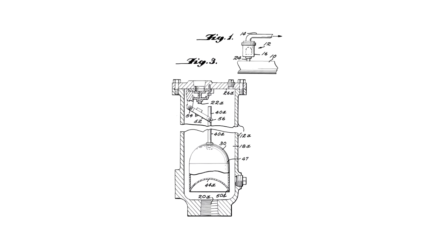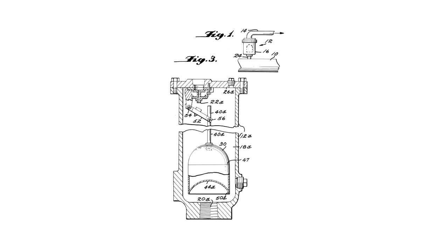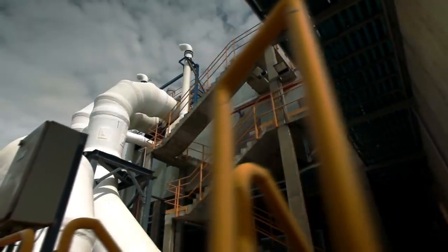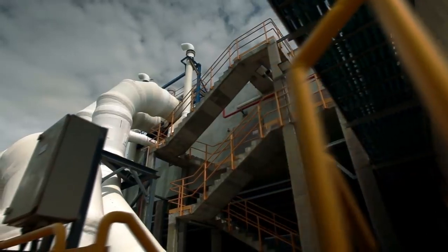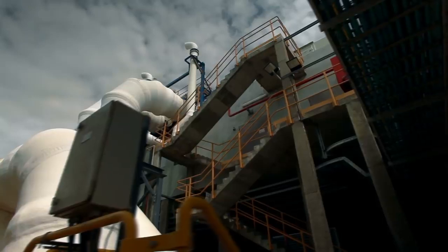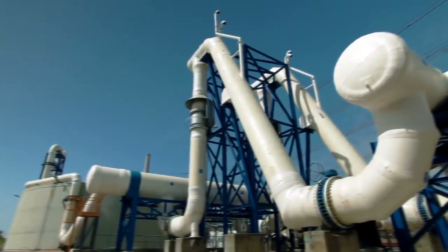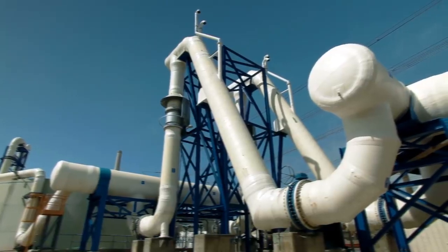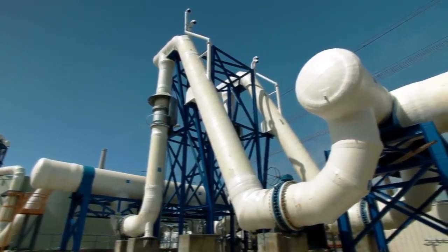Keep an eye out for these type of valves when you're perusing the constructed environment, and now you'll know how they work. The job of an engineer is to take the science and knowledge we have and apply that to design completely new and sometimes untested systems. It almost always involves making assumptions, and if you make bad assumptions, you get bad answers and ultimately bad designs. That's certainly true for airlock, where if you assume that gases don't get into pipes or that they can't constrict the flow, you might design a pipeline that doesn't work.